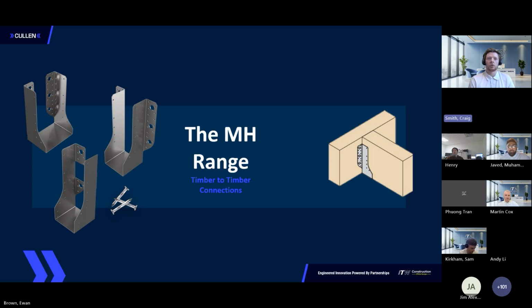And we've got internal and external flange options, which you can see. These are to avoid clashes with surfaces or edges, maybe around openings. And then you can use nails or bolts for higher load requirements. So it's a flexible sort of installation, which is ideal for complex timber to timber connections. Again, using our square twist nails.